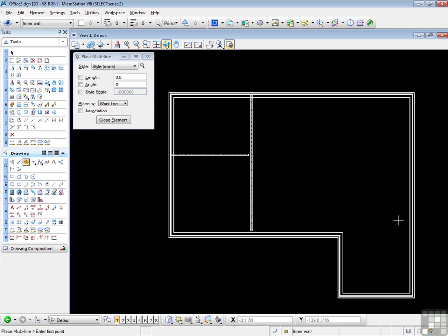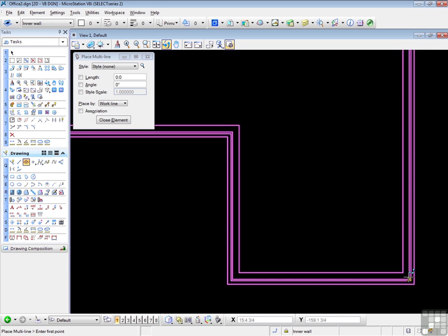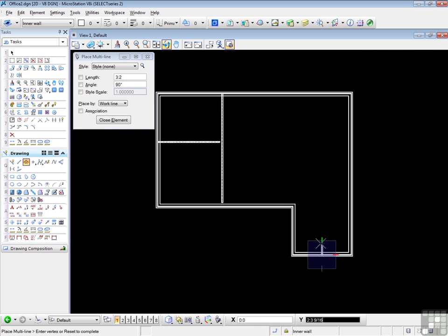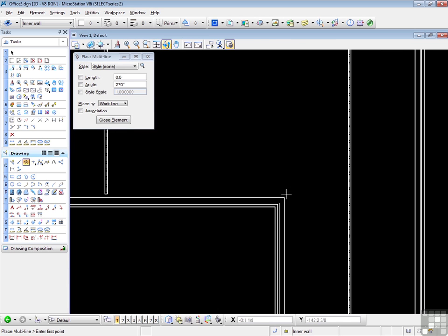Next one is the vertical one here at 9 feet, so we need to go here, F11 and O, run across here by 9 feet. Here comes my wall, take that up, stop it short somewhere about there. Now the next line, or the last line, actually runs from there to there. But if you look carefully at your drawing, you'll see that we have to get the outer edge of the multiline flush with the inner face of the block.